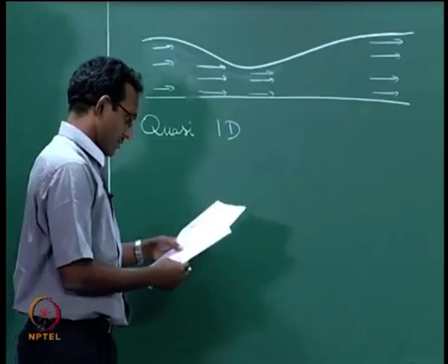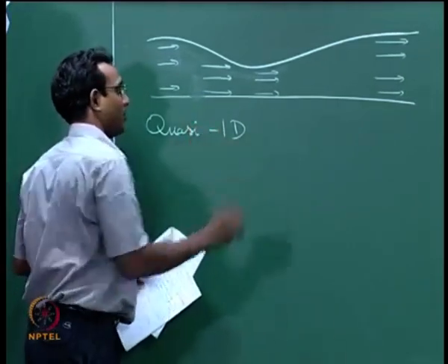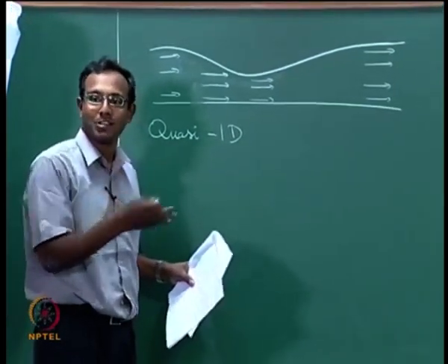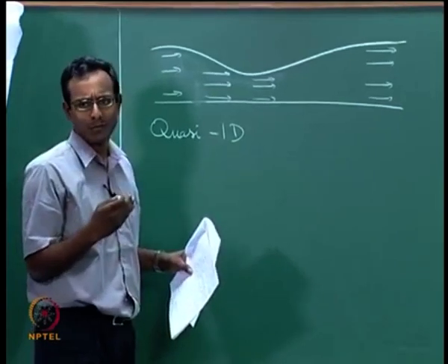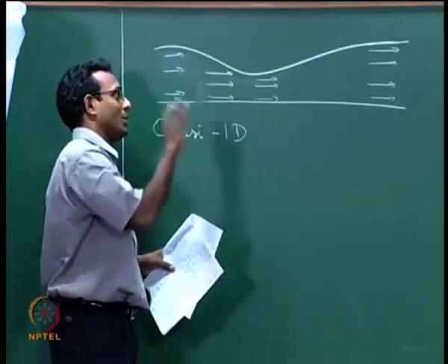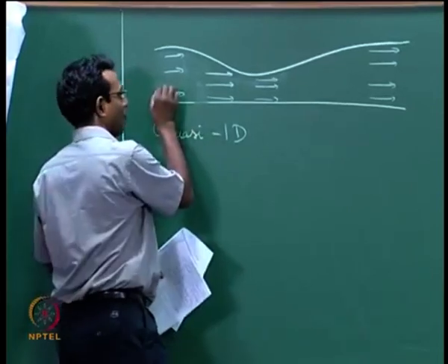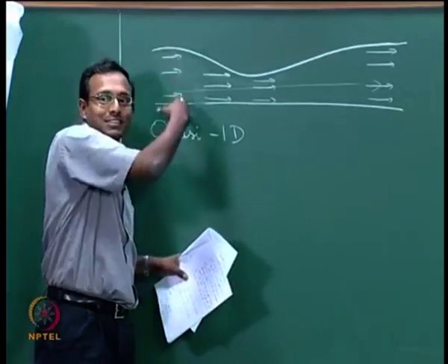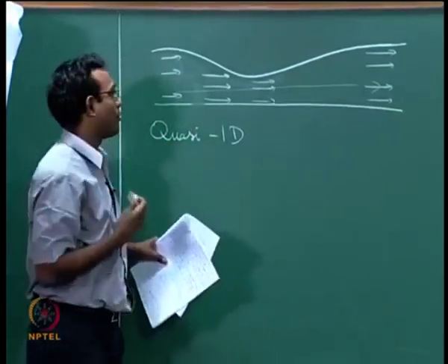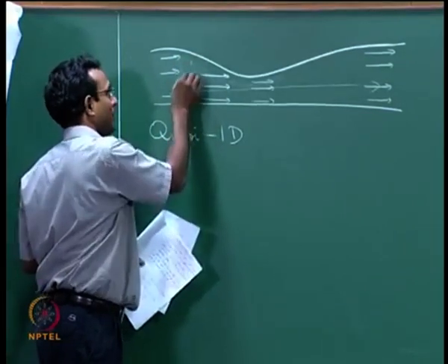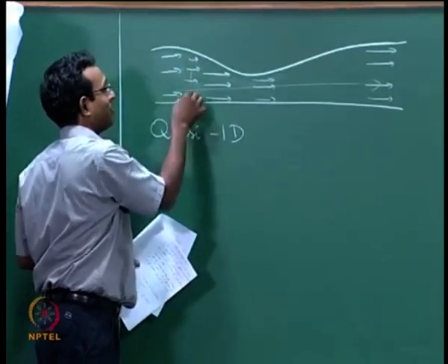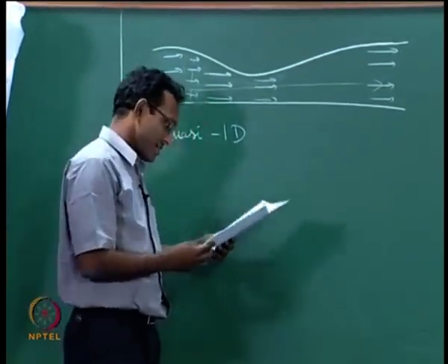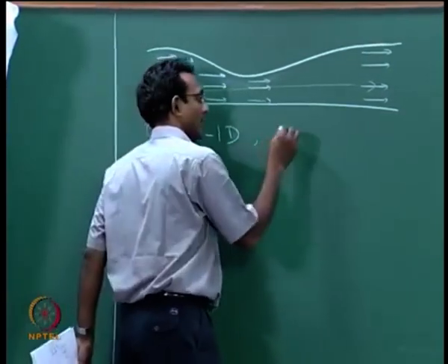Okay. When I say quasi 1D, I am just going to say stream normal direction velocity components are neglected. Stream wise components only. I am going to say all the velocity is along stream wise direction, which is for me in this direction for now. I won't worry about area variation, one side is more than the other side and all that. We will just assume locally I am going to consider some perpendicular line and flow is always perpendicular to it. That is a simple way of thinking about it, easy to convince myself that way. Okay. And of course I am going to also neglect some things.